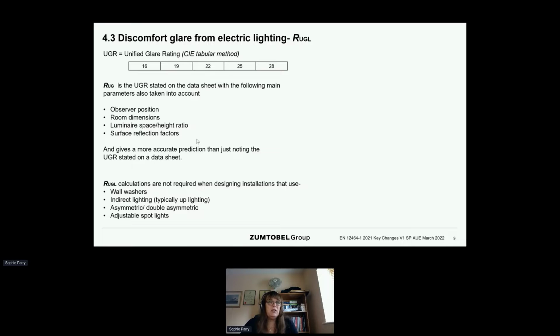Well, it's actually not as easy as that. That is not an absolute number. It's a relative number from when the luminaire was tested in a photometry laboratory, usually at the manufacturer's factory, at a certain height above floor, the measurement would be made, and also the spacing with other luminaires in a larger area where perhaps there's 3 or 4 rows in a large room. So it's very much based on the metrics at the time of test in a laboratory and not your project. So you need to go a little bit further. That UGR 19 or less on the data sheet puts you in the ballpark, but it's not the full story.